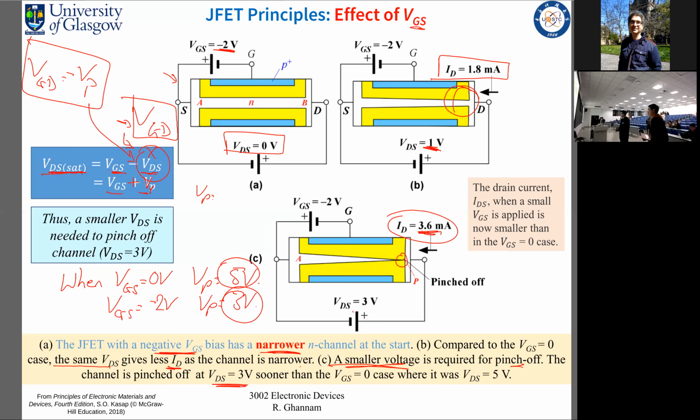Thank you very much for pointing that out. I'll make sure to correct this in the lecture notes. Thank you. I will upload this to Moodle. So this is a typing mistake. This should be VGS minus VGD, and VGD is equal to minus VP, which is why we replace this over here, so it appears as VGS plus VP. Okay, thank you very much.